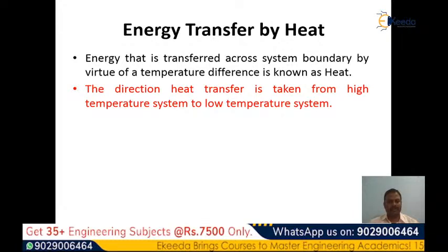In case of convection, when a fluid flows over a surface that is at a different temperature than itself, heat transfer takes place. The direction of heat transfer depends on the relative magnitude of the temperature of the surface and fluid. If the temperature of the surface is higher than the temperature of the fluid, heat transfer takes place from surface to fluid and vice versa.